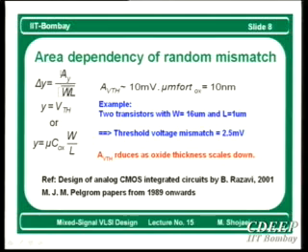And then this coefficient, this parameter, for any parameter you have in the transistor, for example, threshold voltage, mobility, Cox, or sometimes they combine them together and report it, is given in many papers. If you look at Pelgrom's papers and papers that reference them, you can look at citations. You will get all this data for different processes as long as they have been reported in papers. Sometimes foundries don't report it. Okay, this was just an interesting example to see how area will improve matching.